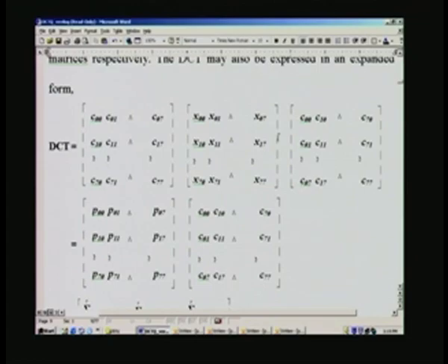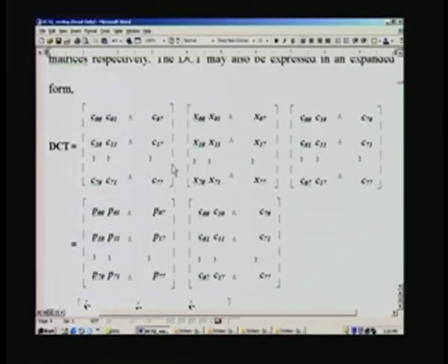So, from a quality point of view, that is the best, but at what cost? Skyrocketing chip cost, because the more the multipliers, the more the chip area. Just now we have seen 8 by 8 itself; had you put 16 by 16, there would be 16 multipliers here, then another 16 there, and so on. The more it is, the more the chip area.